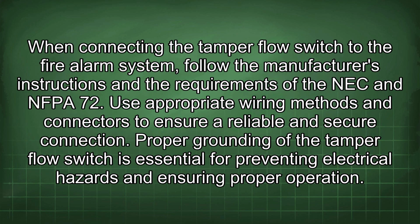When connecting the Tamper flow switch to the fire alarm system, follow the manufacturer's instructions and the requirements of the NEC and NFPA 72. Use appropriate wiring methods and connectors to ensure a reliable and secure connection. Proper grounding of the Tamper flow switch is essential for preventing electrical hazards and ensuring proper operation.